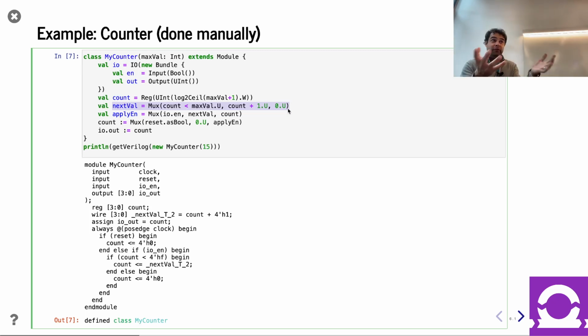It's one of the cool things about generators. We can have this nice abstraction: the user just says, I want a counter with a certain maximum value. And your generator under the hood can be smart and say, I'm going to use this organization versus that organization to take advantage of it. So this is the fun part of generators: you can optimize things. But yes, for powers of 2, that totally will work. Cool. While we're playing with this code, let's appreciate it. Right now we have the maximum value as 15.